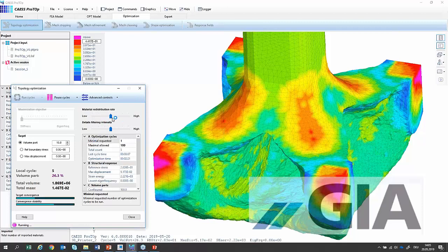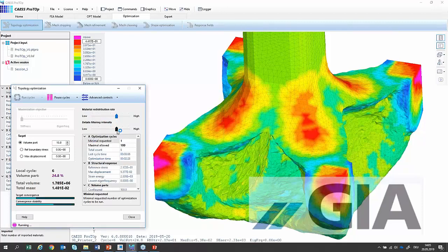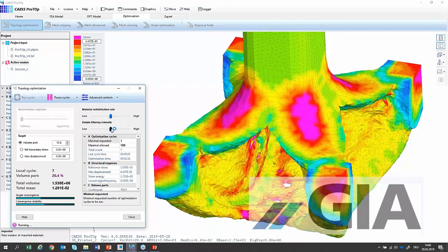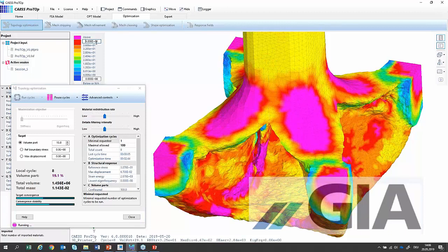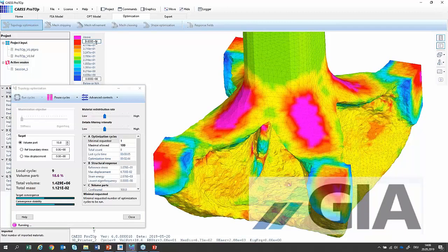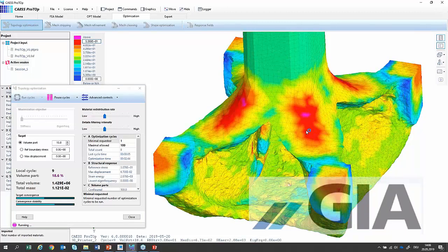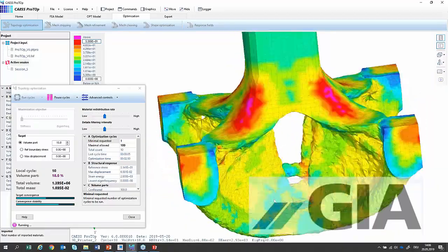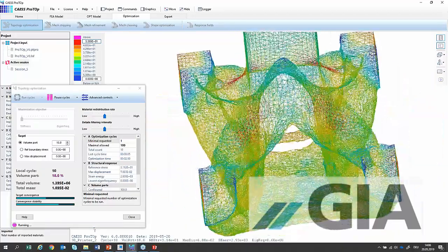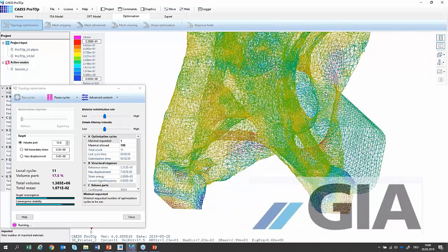Here I can be a little bit more aggressive with the cutting. Okay, going a little bit back with the cutting. It's really playing around with your model. So now it's bringing in some holes. The stresses will increase here. I can change the legend levels of my stresses. Okay, and here I can see a very interesting solution if I have a 3D printer at home.